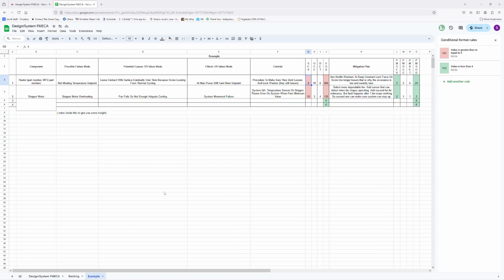Okay, so let's go back to examples. Let's go through examples. Here, heater part number, manufacturer, and manufacturer part number. Then basically, for severity, I put 8. This is basically system down, and now you have to take all this stuff apart. There are mitigations, like I talked about in the safety section for this heater, to keep it safe. But to keep it safe, there are more things you have to remove: tooled interlock covers, other shielding, things like that to prevent fires. You have to remove all that and make sure you document all the screws you're taking out, follow the procedure, do all this stuff.